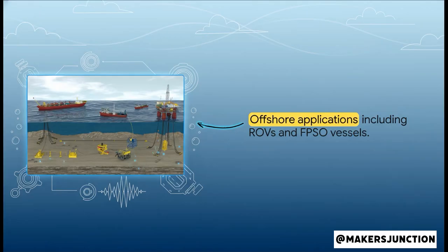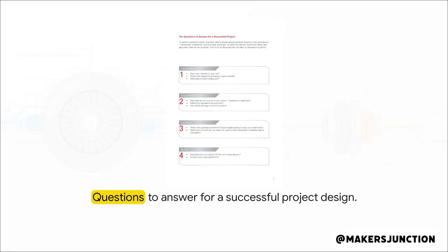Moving from the sky all the way down to the crushing depths of the ocean floor, combined slip rings and FORJs are just as vital for marine exploration. They allow remotely operated vehicles, ROVs, to transmit high-definition seismic surveying data, miles up a tether to floating production, storage, and offloading vessels bobbing on the surface. And these units have to be incredibly rugged, often sealed to strict IP68 standards, just to keep out the highly pressurized saltwater.